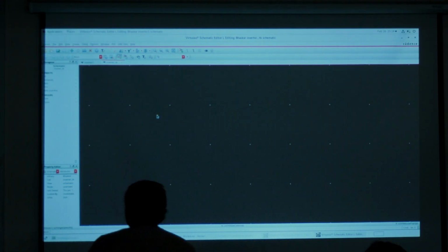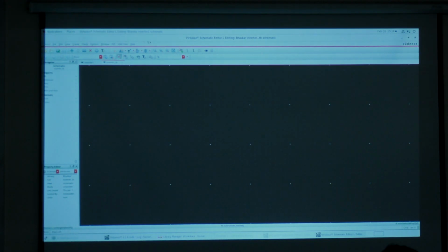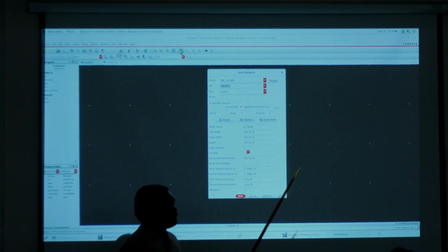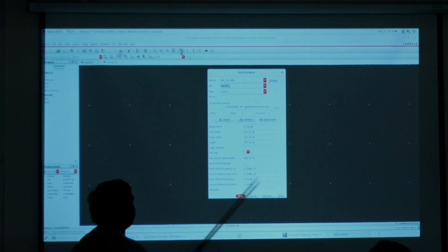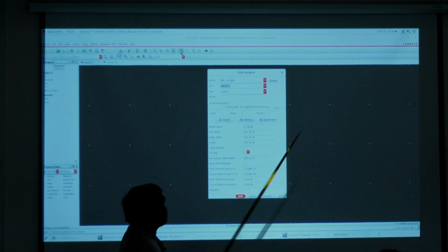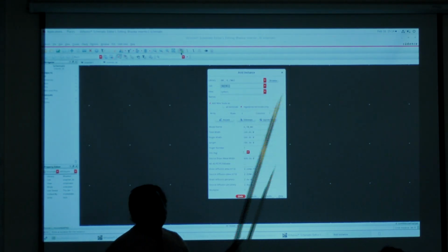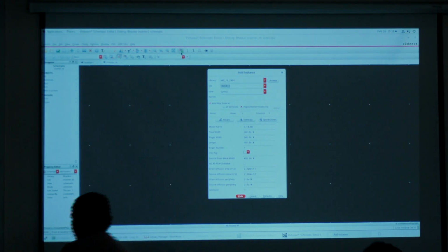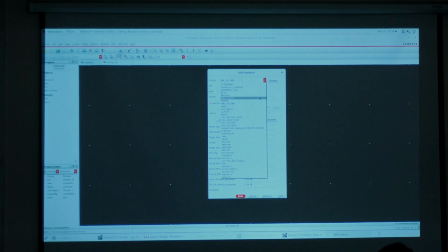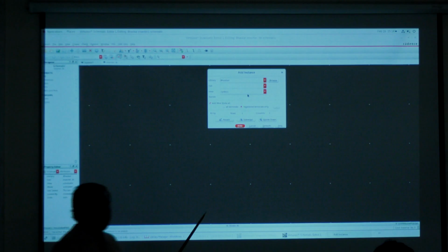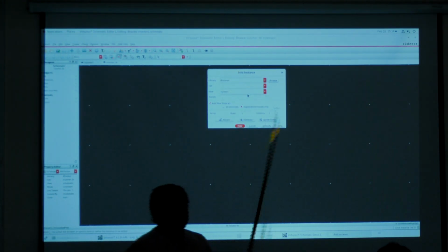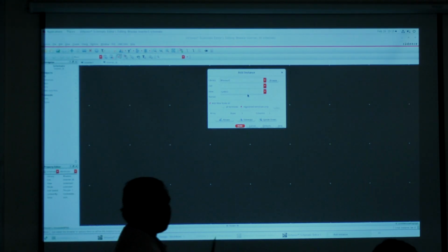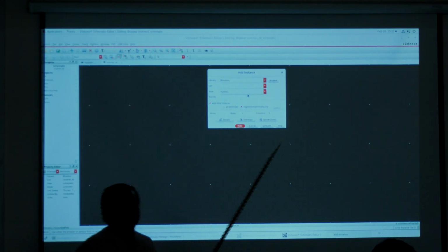Now here we call the instance, no? We have added the instance, no? Here we clicked and we have added the instance. You need to select this one, add instance. Here library. The library which you created, a library name, no? You select your library there, because the schematic which we designed is in our library, so we need to call that symbol to here.